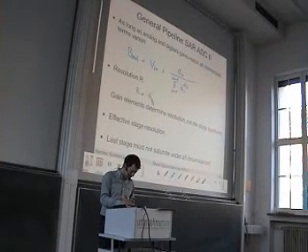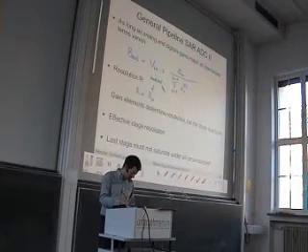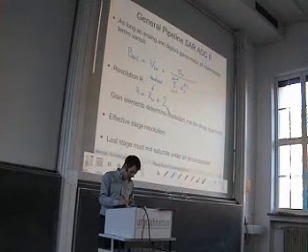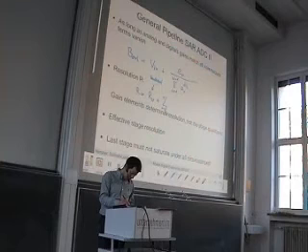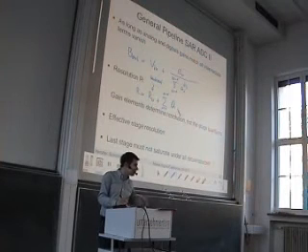given by the resolution of the back-end ADC. So this is the back-end, the last one, plus the stage resolution contributed by each stage. So we have to sum over all stages. And we have seen that the stage resolution is the logarithm of the gain.